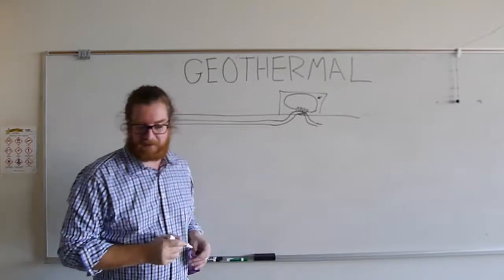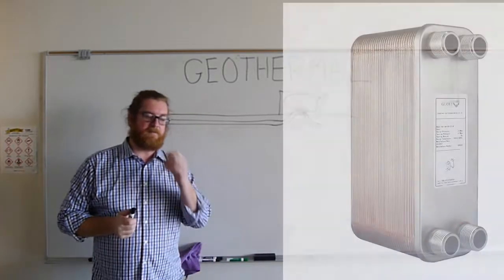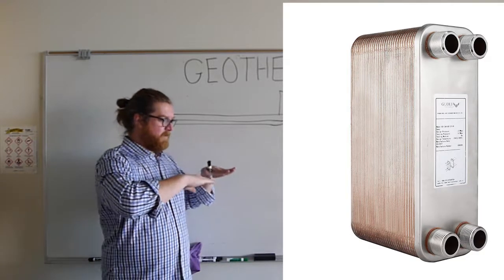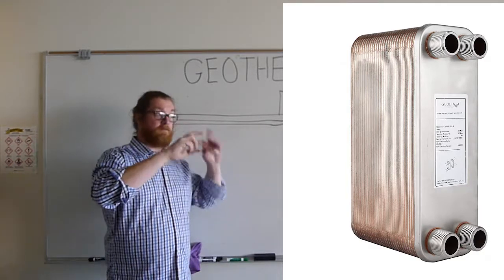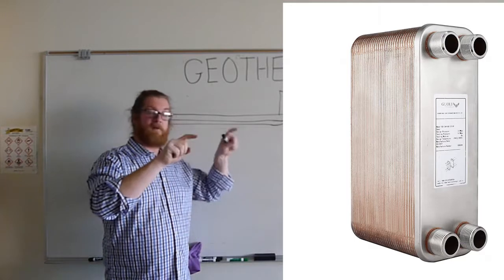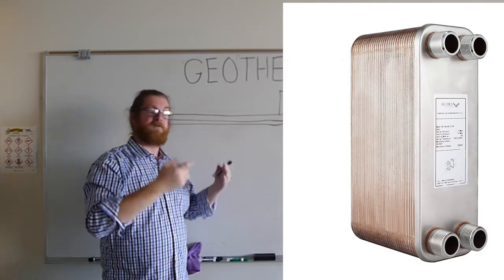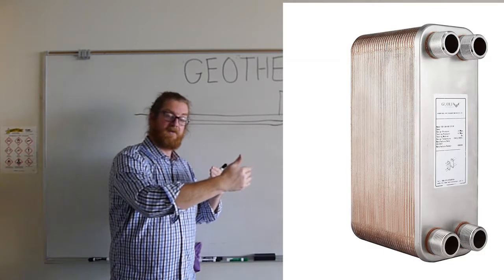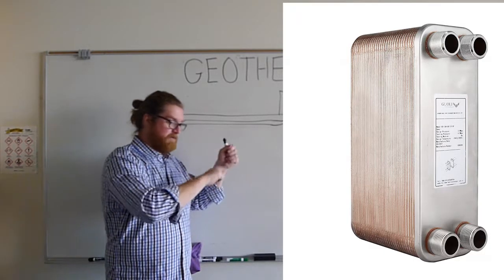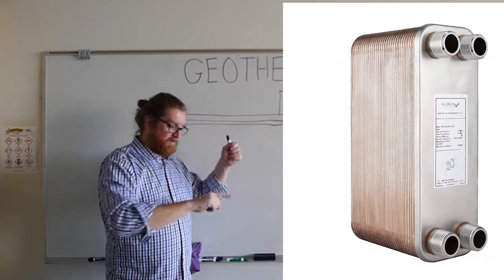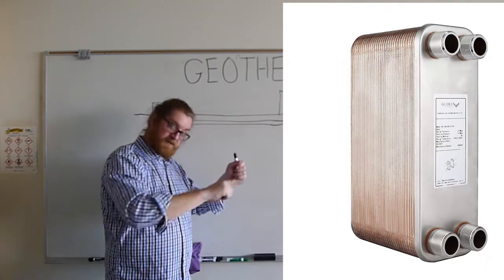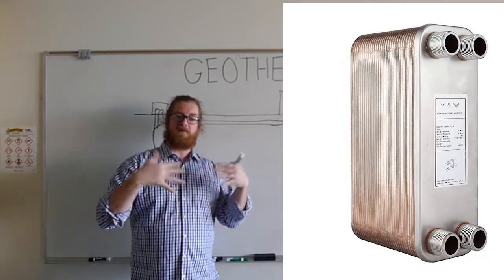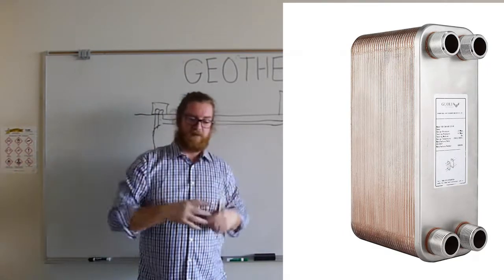I know that sounds pretty goofy, but you can see here, this is a type of heat exchanger right here. This is called a plate exchanger, and it has 4 ports, right? One is in and out of one system and one is in and out of another system, and never do the two groups of water ever meet one another. So water travels through every other layer of one system, and then in the other system, the water travels through every other layer. Kind of like a half shuffled deck of cards, right? They're all between one another.